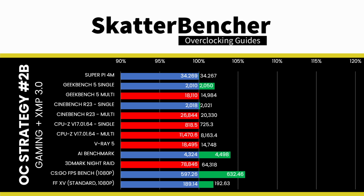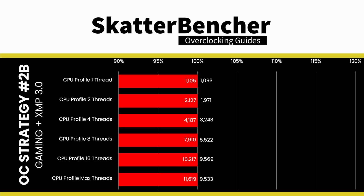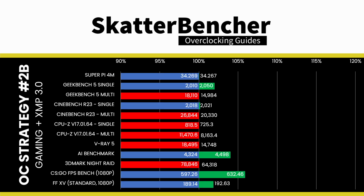The performance is a mixed bag with the gaming profile. As expected, we see the largest performance losses in multi-threaded benchmark applications, but not all of our results are that straightforward. In CPU-Z single, we lose more than 10% performance despite running the same P-core frequency as default settings. AI benchmark performance in fact increased by about 4%, despite it being a multi-threaded benchmark application.